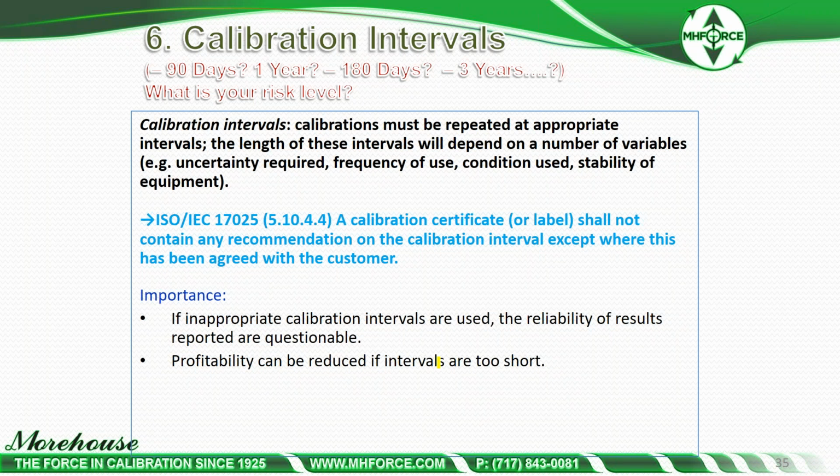It's always funny up front. Somebody will see an equipment cost of $800 versus $1,600. They go with the $800 option, and it'll cost them 4 or 5 times more in calibration because they'll have to have it calibrated every 6 months instead of every 2 years or every year. So the frequencies will just be double or quadruple.